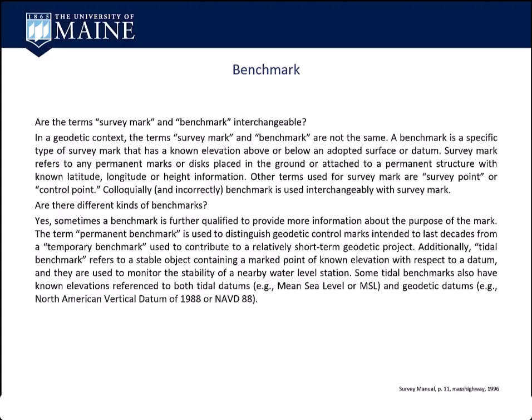So what's a benchmark? We talked about it earlier. So survey mark, benchmark, they're not the same. Benchmark is a vertical control. It's any number of physical things. If you do deformation studies, you're going to have a lot of benchmarks.